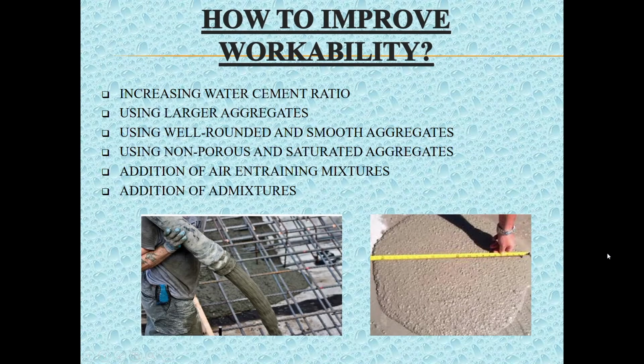Till now, we have seen how various factors affect workability of concrete. Let's see how to enhance the workability. Workability can be upgraded with the use of large-sized, well-rounded, smooth and non-porous aggregates. It can also be developed by increasing the water-cement ratio and adding air-entraining admixtures.